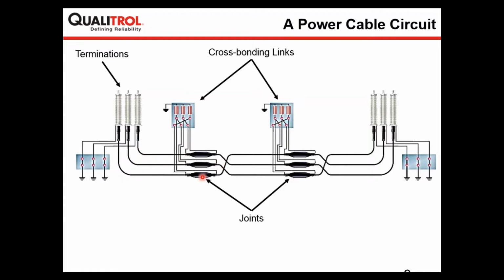In a long cable network, whether it is a transmission network or a distribution network, at the joint location there can be solid grounding. And if it is a transmission network, there can be cross bonding. The reason for doing grounding and cross bonding is to avoid circulating currents in the power circuit, and if you have circulating currents, it will lead to overheating of the power cable.